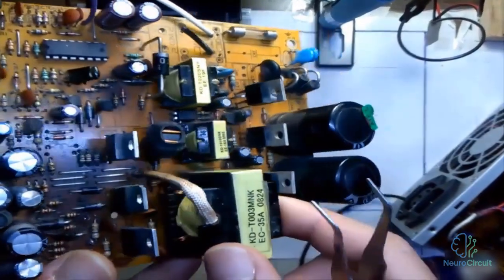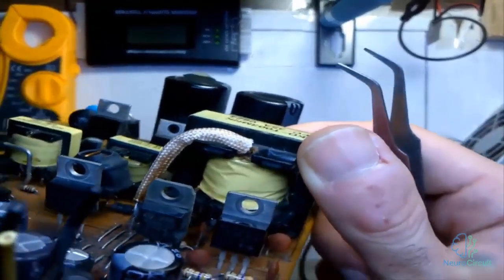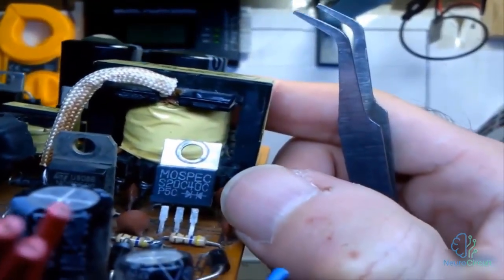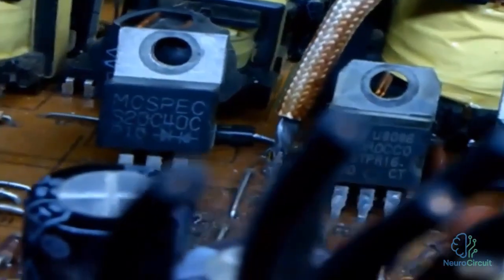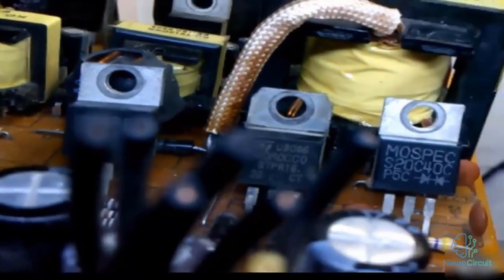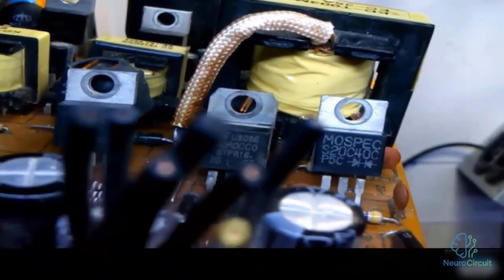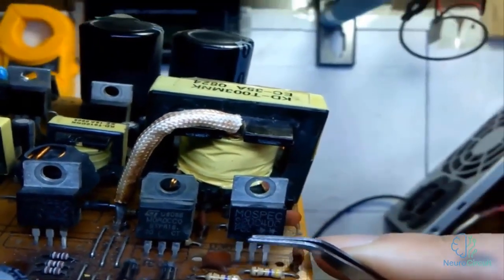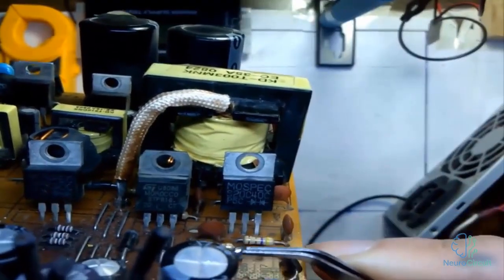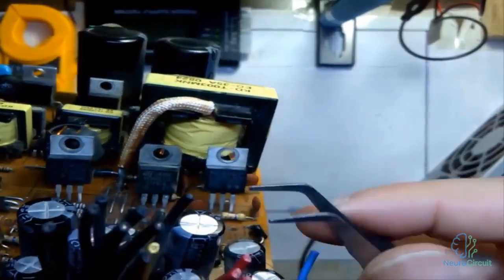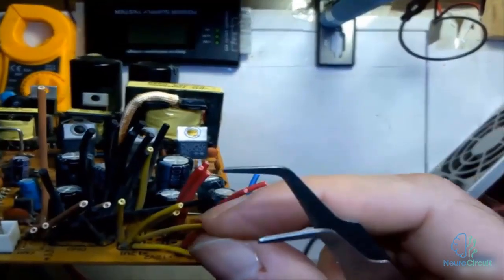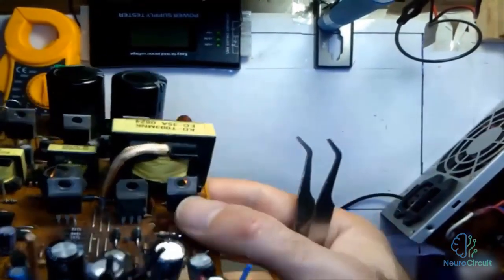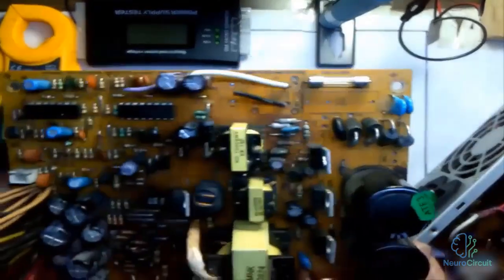Now to make this electricity usable, they use Schottky diodes for the output electricity, which you can see here. In this image you can see it completely, and as you can see you can even recognize it by its symbol. You can identify that the type of diodes are Schottky diodes. For example, the Schottky diode used here is a common cathode type. So the positive electricity passes through the Schottky diode and is once again converted into DC electricity. And its current is limited by resistors and capacitors. The desired voltage is generated and it is delivered at the output. And that's basically how a power supply works.